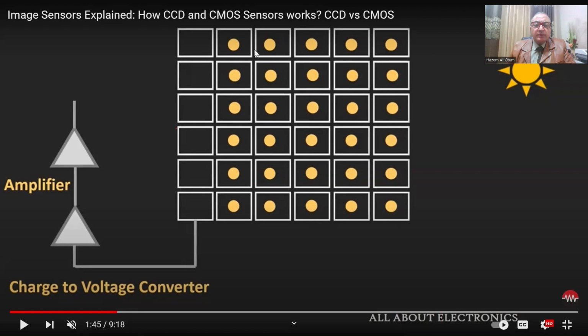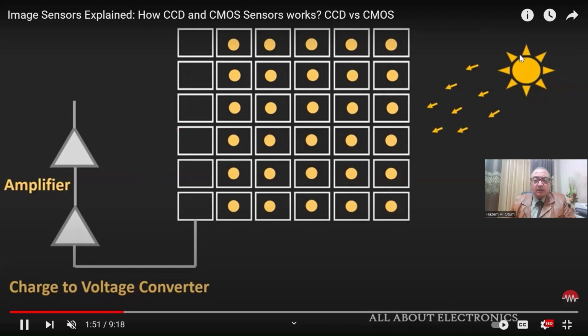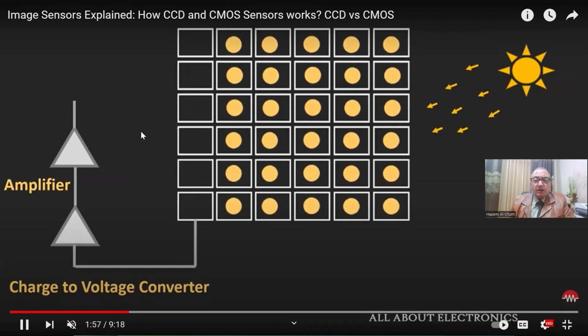Now, this is maybe a good tutorial to have as an example on CCD cameras. In this case, the readout process is done column-wise, and this is also available. Then the output is read out by the amplifiers that will be sent further for processing and for storing, maybe, or transmitting to other places. As you see here, if you look at the pixel wells or the potential wells, you see that these wells are when the light is incident.